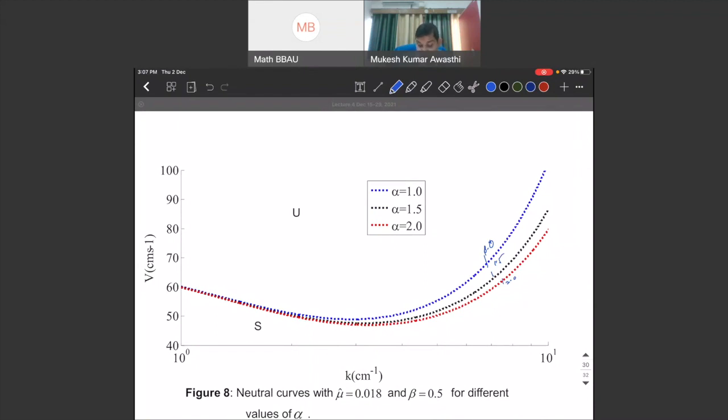That means heat transfer has a destabilizing effect on the stability of the system in the Kelvin-Helmholtz instability. It is because when the heat transfer increases, the vaporization and condensation make the interface more unstable. It increases the relative velocity of the interface.